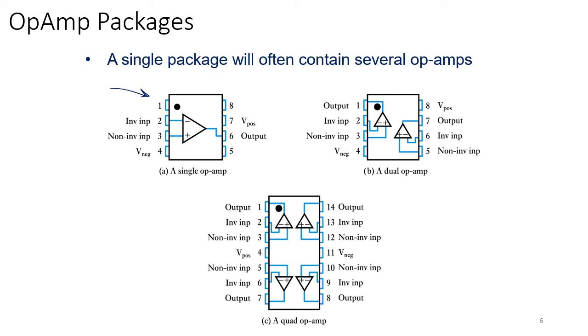So basically, pin number 2 is connected to the inverting input or the negative input, 3 is connected to the positive input, and 6 is connected to the output. And then you can see that the positive supply is connected to 7 and negative supply is connected to 4. In this case, 1, 8, and 5 are connected to nothing. So it's a package where, when you look under the hood, when you scratch off the ceramic, you will see that three of the pins are not connected to anything, and that's okay, right? It's just that this is how the company is selling their product, right?